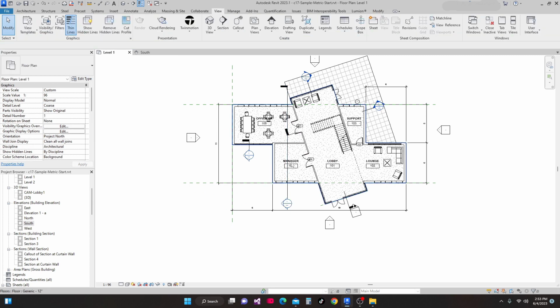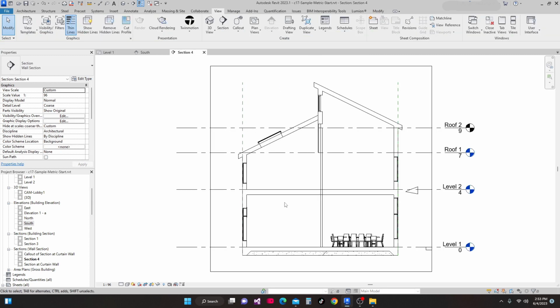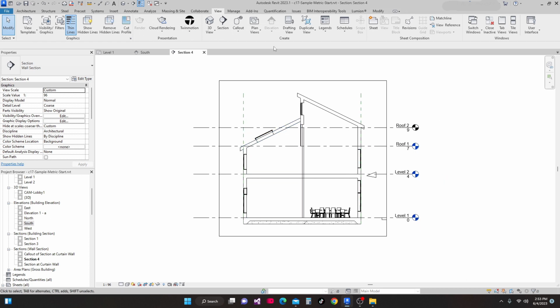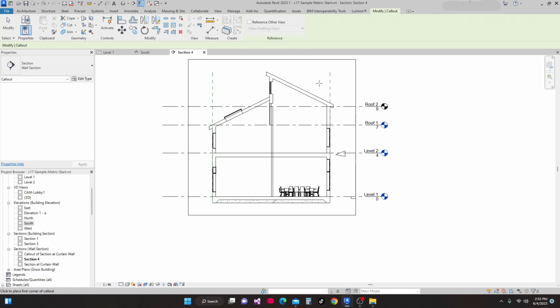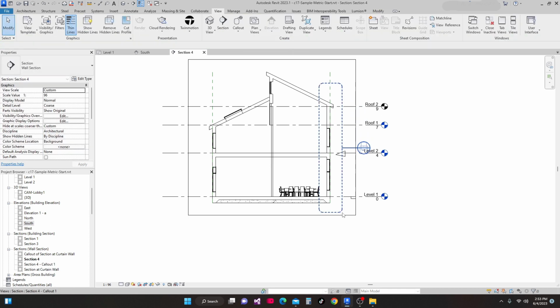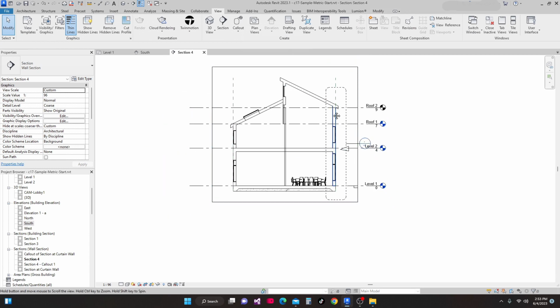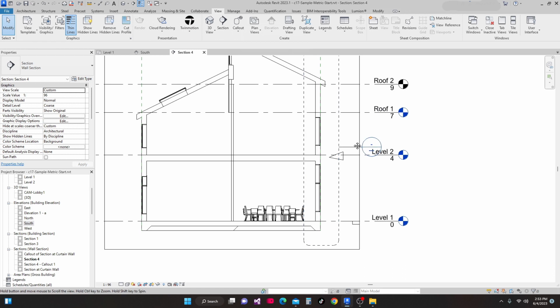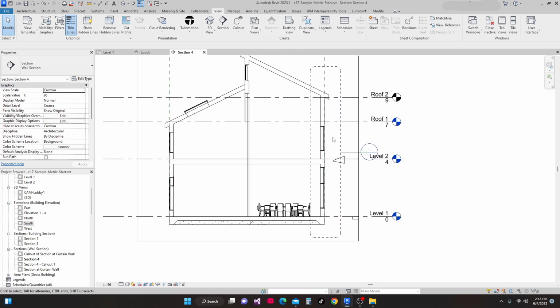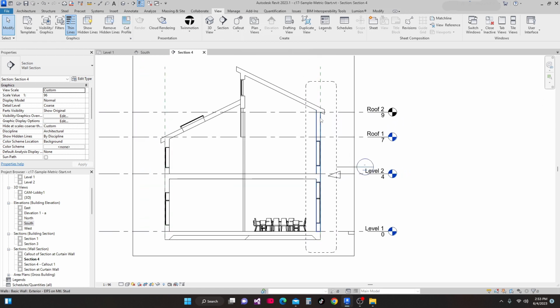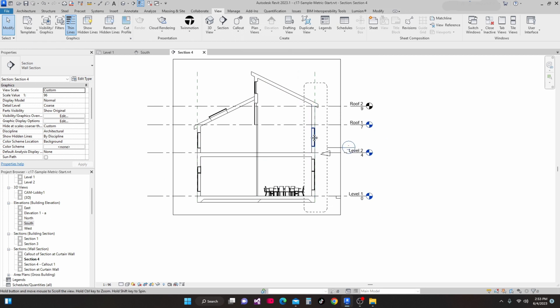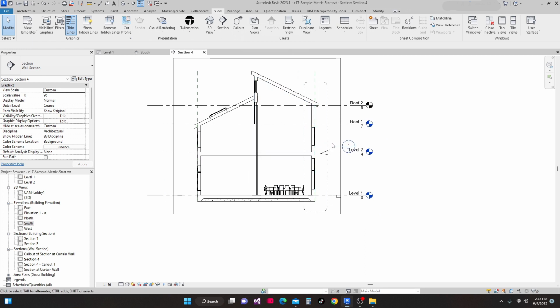And then I double click it and call outs. So let's make a call outs. I go to view and call outs and make a call outs here. This call out is used to separate this from our sections and make more detail. If you have something to emphasize in this part, we need to make a call out and make more detail.